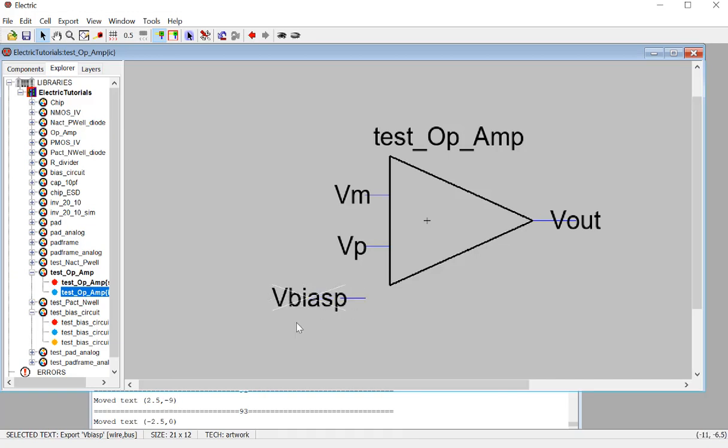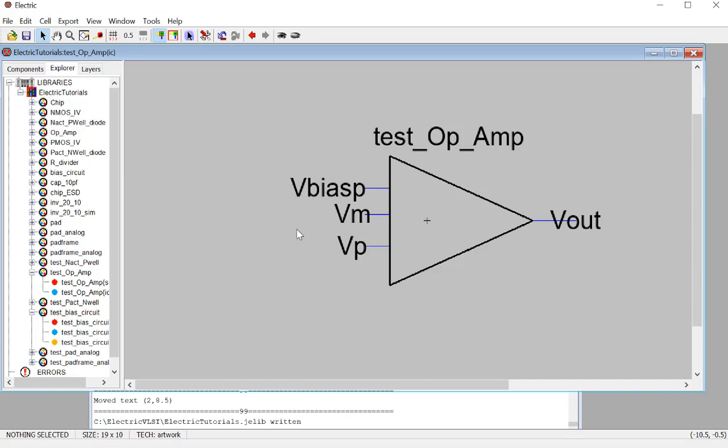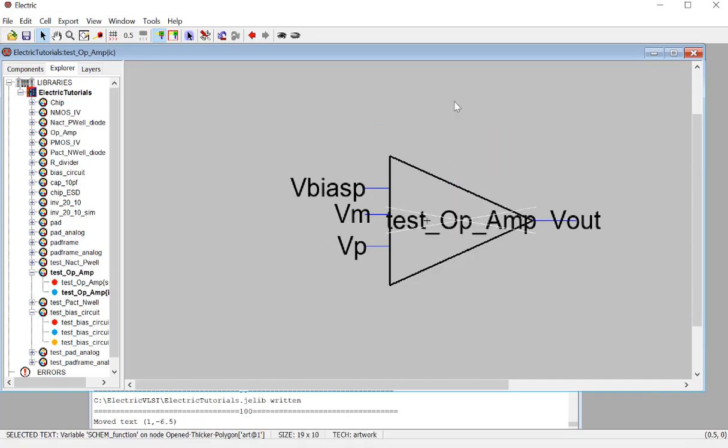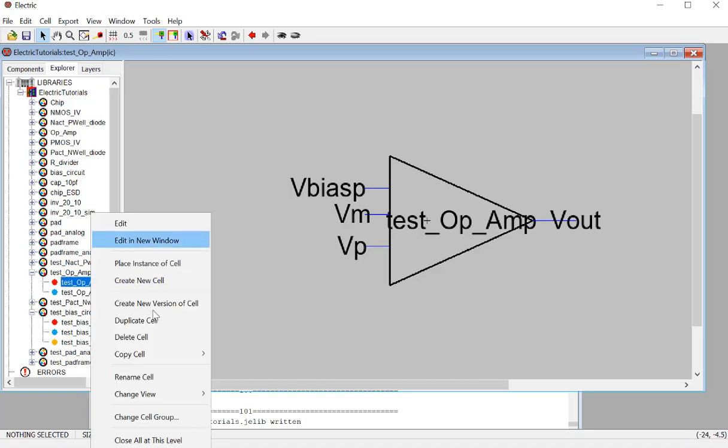This is kind of a special thing. When we are using the 741, the commercial product, we don't have this thing, right? The reason is we usually have a startup biasing circuit inside of the transistor, so we don't need this. You don't need to bias it manually using an external resistor, but we don't have it here. We just want to make it easier to design, so I didn't include that startup circuit in here. So the icon is ready, schematic is ready, so the next step should be a layout view.